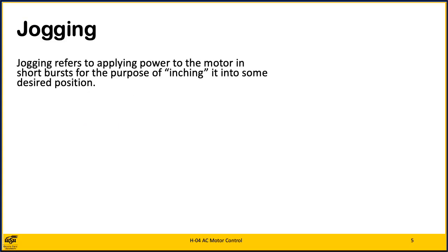Jogging refers to applying power to the motor in short bursts for the purpose of inching it into some desired position. For example, a commercial mixer might need to be jogged into a certain position so the blades can be replaced, or a motor driving a large shaft might need to be jogged to get the keyway lined up with the mating part.